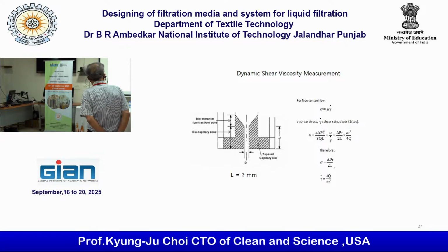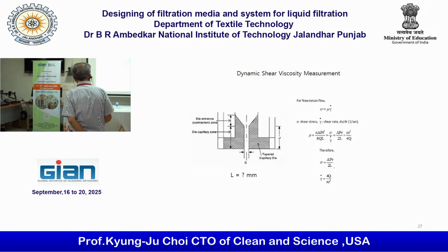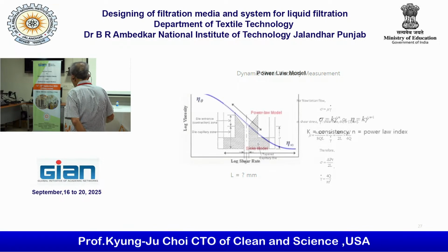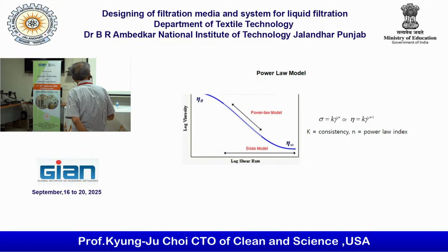Here. This is the diameter of the capillary. This is the length. We used this equation yesterday in order to get the shear viscosity. So shear stress, normally eta, but if it is the so-called power law, then sometimes K, but it's the same as the viscosity.